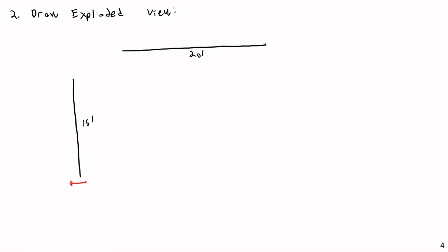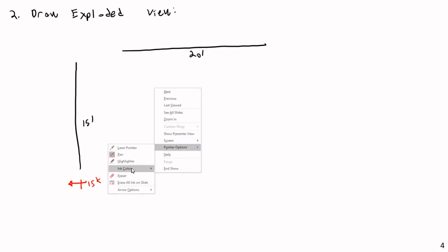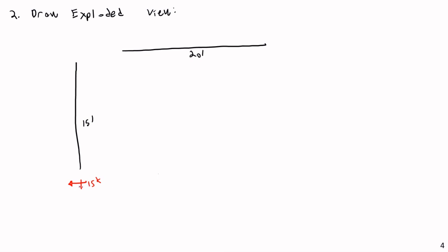So I have my reaction Ax, which is 15 kips. I have a vertical reaction Ay, which is, oh, I managed to erase my column there, that's not good. Don't want any columns vanishing on us. Ay then is going to be 14.375 kips. Cy then is going to be 25.625 kips.